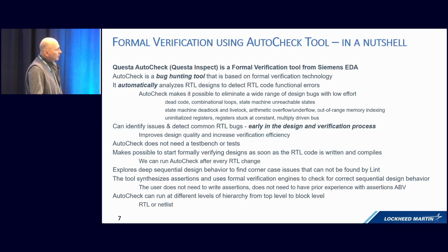Then we can integrate with whatever CI/CD we want and have run AutoCheck on every RTL change. It's important to stress that it is much more than lint. It uses a formal engine, and lint is not using a formal engine, so it can explore sequential behavior of the design.